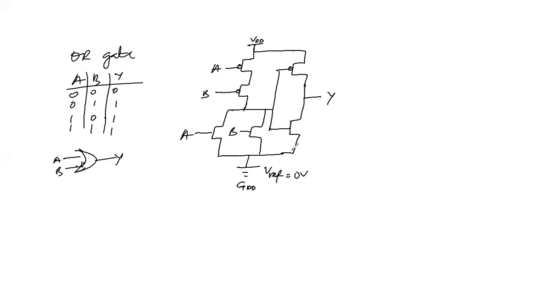So we have the gate, the source, and the drain. Okay, so now for the OR gate, for 0 input, this is seen as a short circuit. So the voltage level is the same here, this is 1, and then since 1 is appearing here, this operates as an open circuit. So what we get here is 0, right?